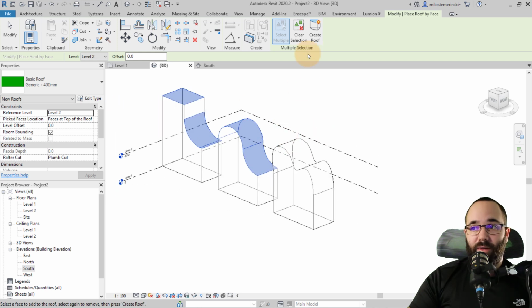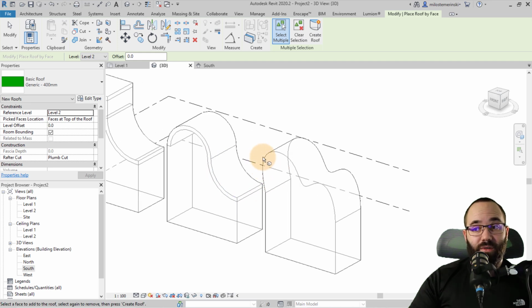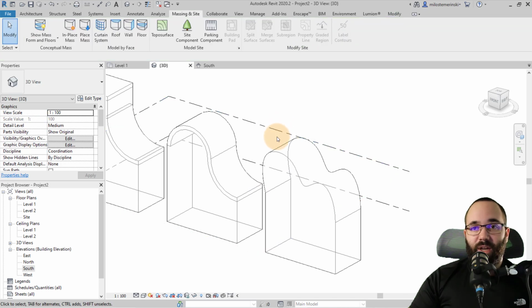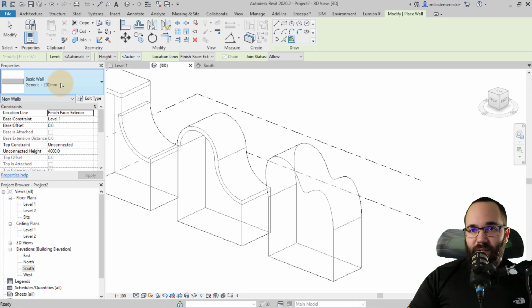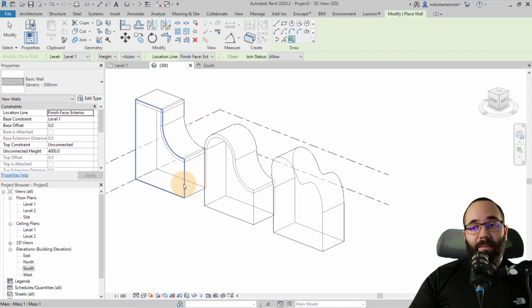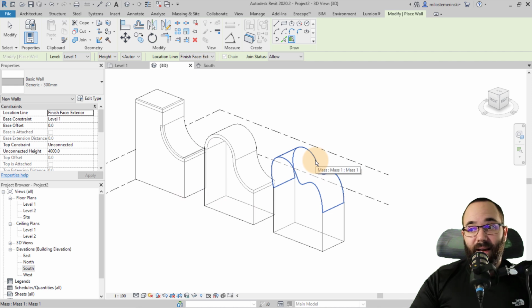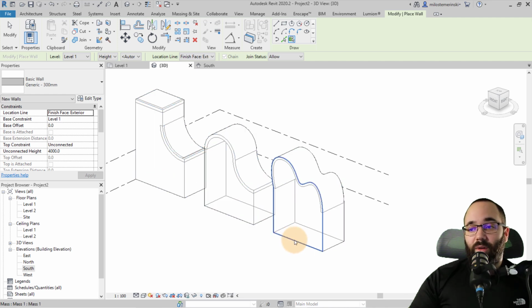They basically are not going to follow vertical surfaces, and if you change a surface to have that vertical edge like we did here, it's going to give you issues. Now you can of course fix that by using a wall. So if I switch this to a wall, let's go with this one, I can now pick this vertical surface here. I can pick regular walls like these here, but also I can pick out this surface here. So this surface is going to work. So that's just something that you'll notice.